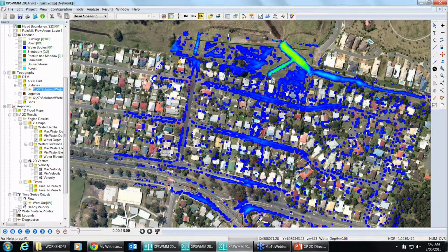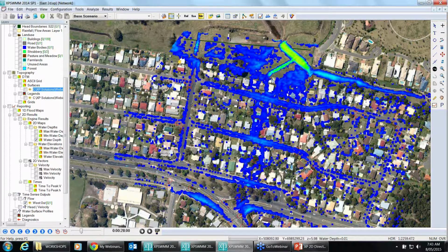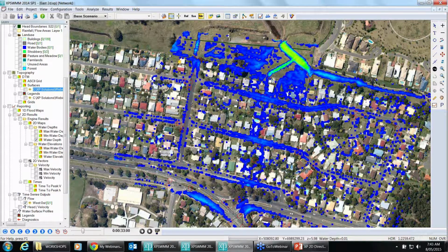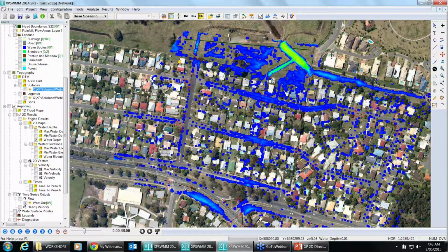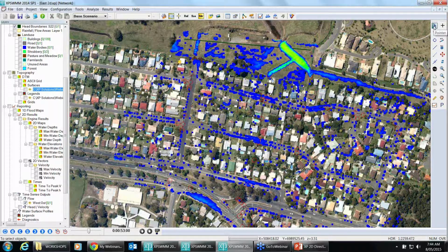We're starting to see some flow that's going to bridge between these two roads, and effectively that's giving us what I'll call cross catchment flow. You'd like to think that the curb and channel would confine these flows, but look, we're getting depths of water that unfortunately are affecting a handful of properties and that identifiable low point through the site. And the direct rainfall method is certainly a very appropriate tool to highlight that kind of relationship inside a catchment.